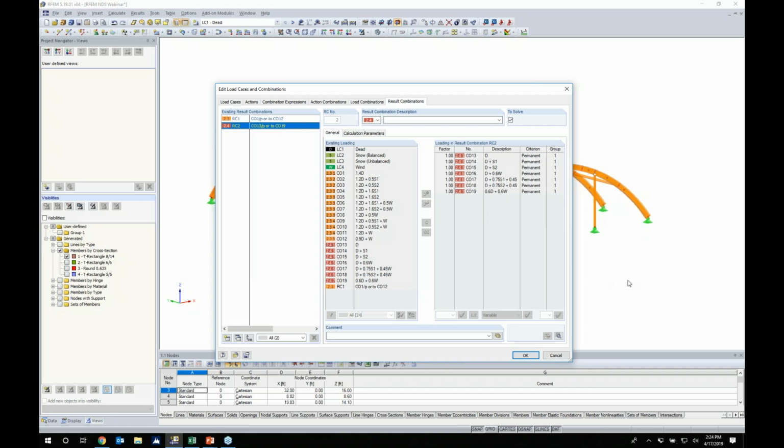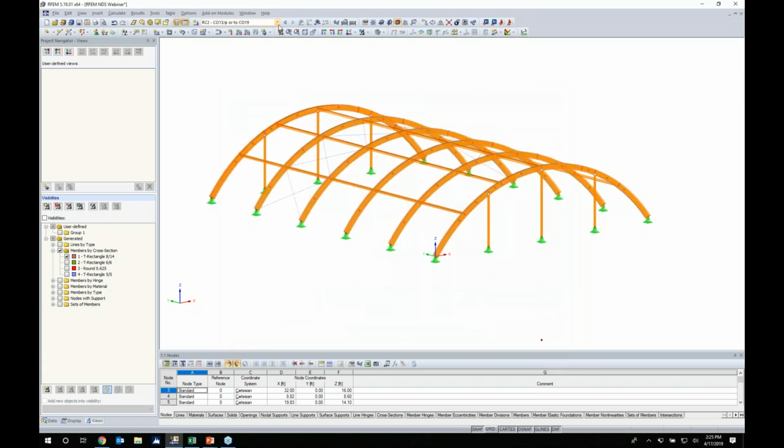This is just going to show us back, once we do run an analysis, the maximum forces, maximum deflections, for example, of all these load combinations considered. So now that we have defined these different load cases and combinations, you can see them in our drop-down box, but we actually need to apply the loads to the structure.